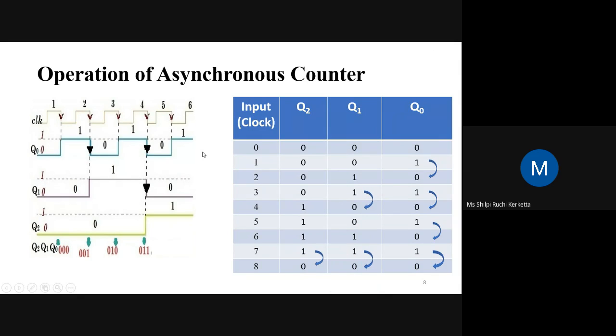This part is the clock. Initially we gave a 0. So where is the first negative edge? The first negative edge is here. That's why here from 0 it will change to 1, and there is a delay of 2. Here we are getting two zeros. Understood this part? This is the clock for the second part.